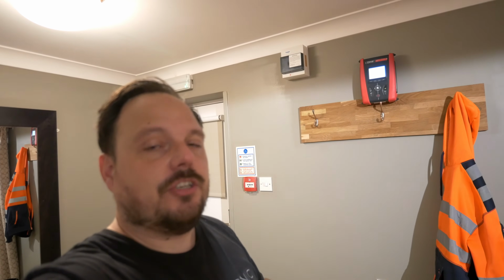Today we're going to have a look at an EICR on a very simple installation, a couple of circuits. We're going to run through it. We've got a ring final circuit, a lighting radial circuit. It'll be interesting to see what values we get, compare them both live and dead, and show how they get inputted into an electrical installation condition report.